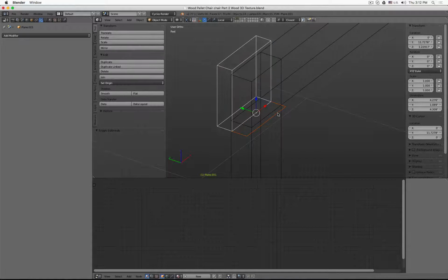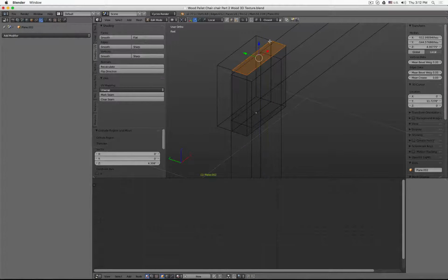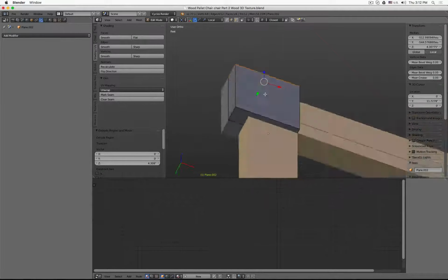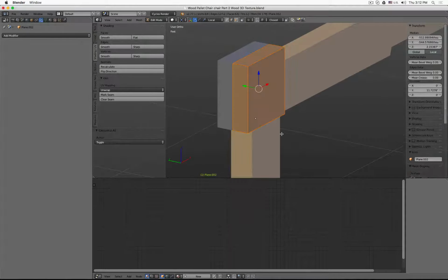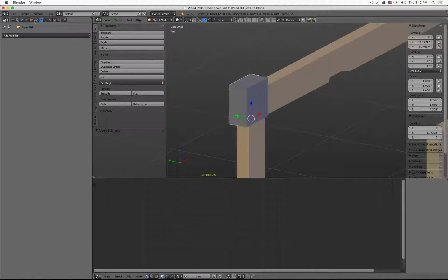Perfect. Good. Now we have to go to here, select everything. That's the other second object. E, extrude it up. We can snap to this height. Let's check. Okay, there, it didn't open that face. AA, just to double check, recalculate. Good. And best practice,